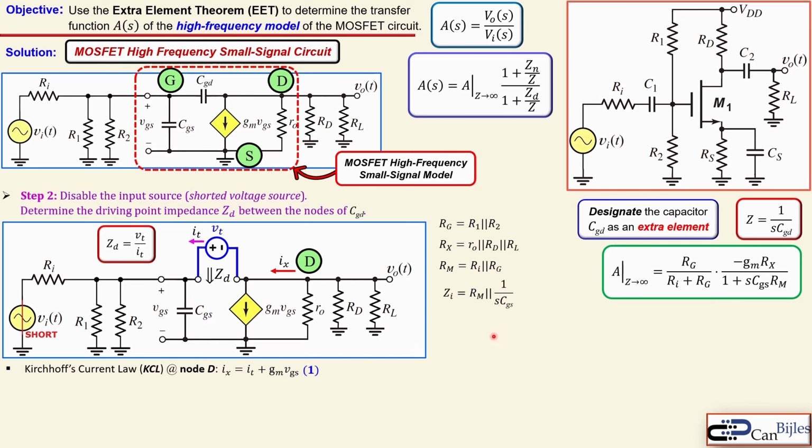Okay, now that's that. Now we can use Ohm's law, because Ohm's law can be used here to determine the gate to source voltage expressed in our new impedance and also our IT. Because this current here will be flowing in the complete branch here together with this Zi. So that's what we have here. And let's call this equation number 2.